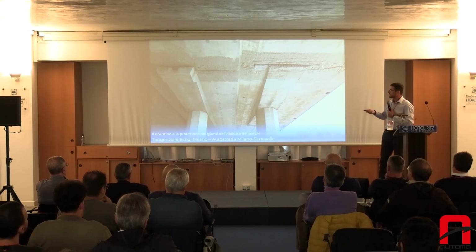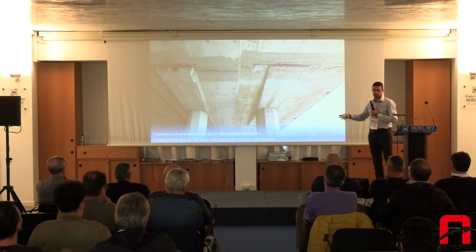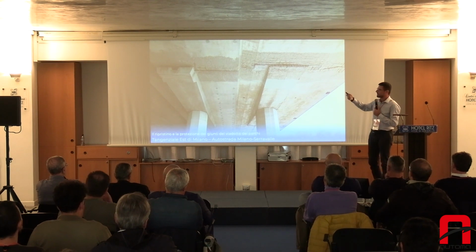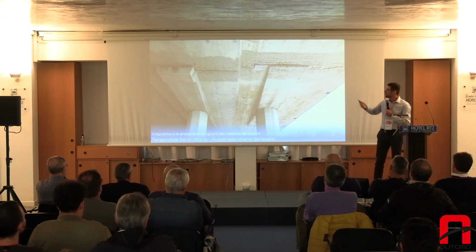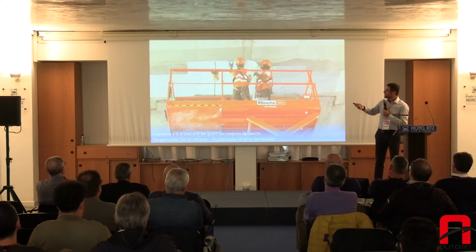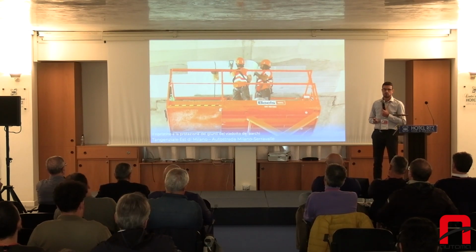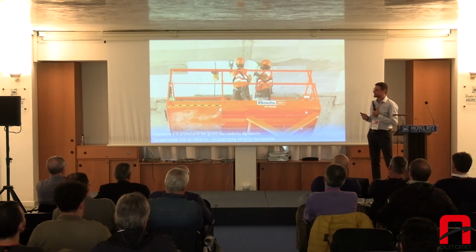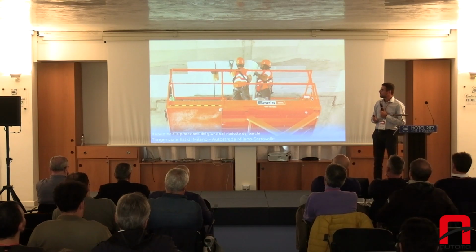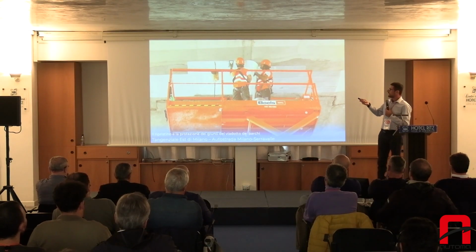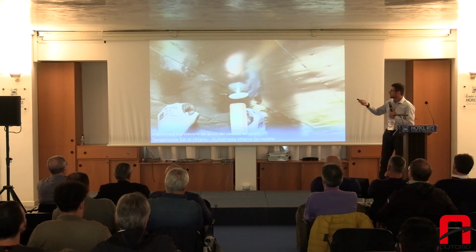Based on this, we decided how to restore these joints. We, of course, provide mortar for restoration activities of the degraded joints. And we also provided the cathodic protection system suitably sized. And the customer decided to protect an area of about 2 meters on the right and on the left of the joint by using the external zinc sheet. Here you see some pictures of the work.